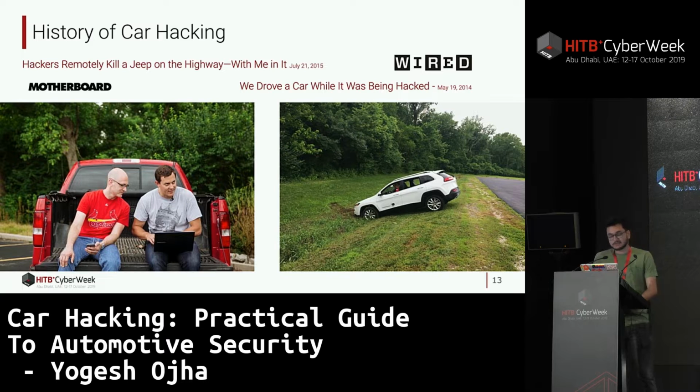They demonstrated that it was possible to remotely control the vehicle control unit from a telematics unit that had a cellular network connection. They gained access from the cellular network to the intra-vehicular network through the CAN bus. Then they identified that the automotive data packets should be protected with mechanisms like TLS and encryption, but sadly it was not addressed by any of the car manufacturers.